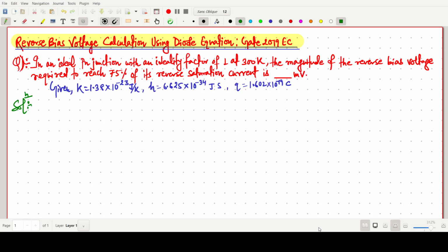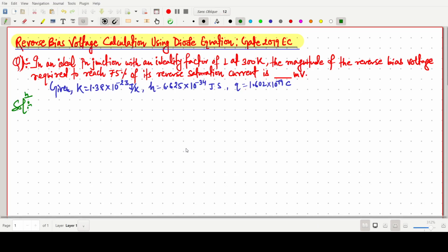Welcome everyone. In this video lecture, we will solve a GATE 2019 EC question in which we have to find the reverse bias voltage using the diode equation. So basically, we will use the diode equation to find out the reverse bias voltage. So the question is: in an ideal PN junction with an ideality factor 1 at 300 Kelvin, the magnitude of reverse bias voltage required to reach 75% of its reverse saturation current.